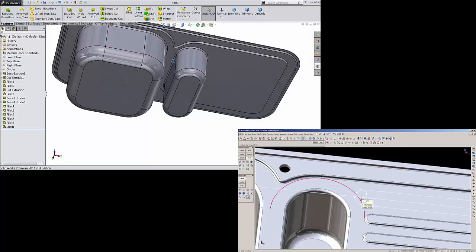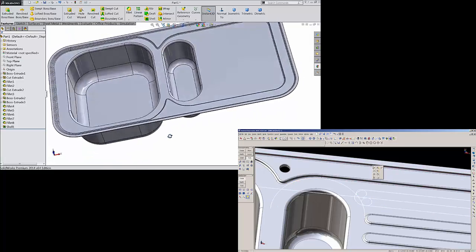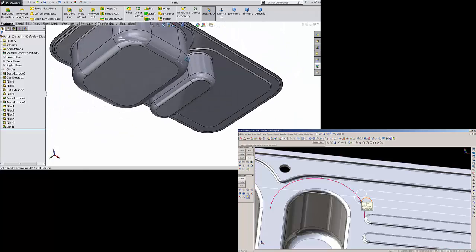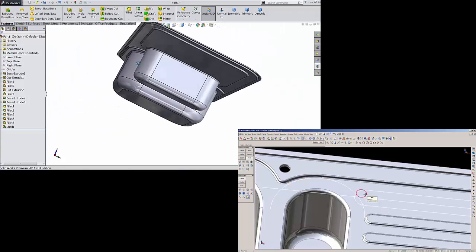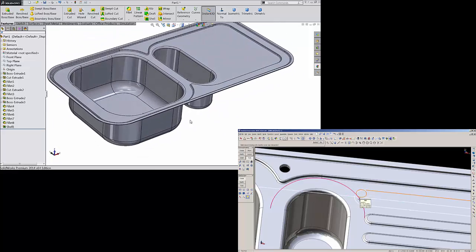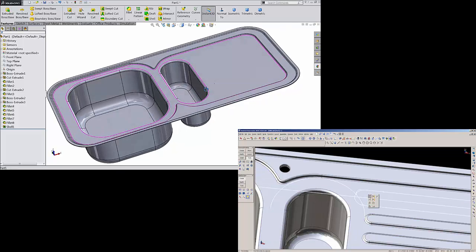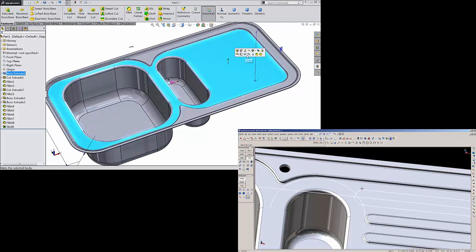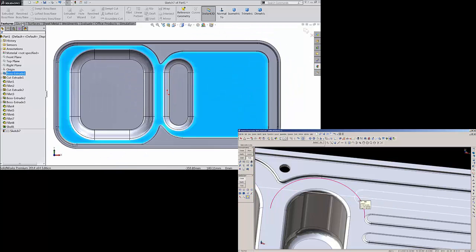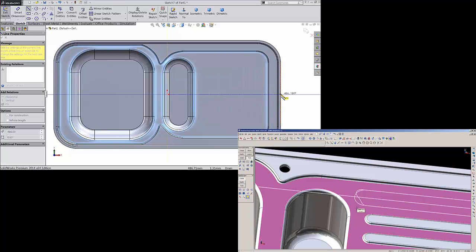See, our basin already took the shape. This is our basin. You can see it here. With the help of a simple command we created this basin. Now let's make some grill marks on this face. So select this face, sketch, and first draw a center line.